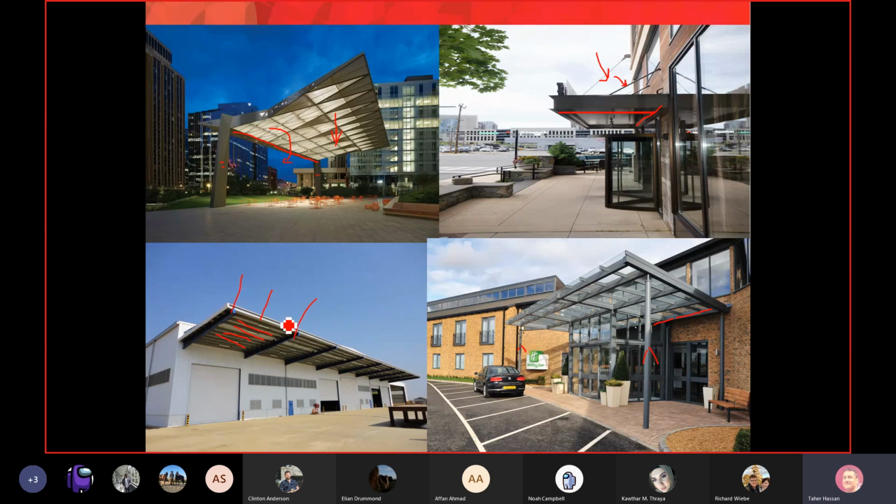The load will go from the joist to the outrigger in blue, and I bet there are some columns here: a column here, a column here, and a column here. Those outriggers in blue simply cause bending on the column, not torsion on the beam. Look at the framing and you will know.